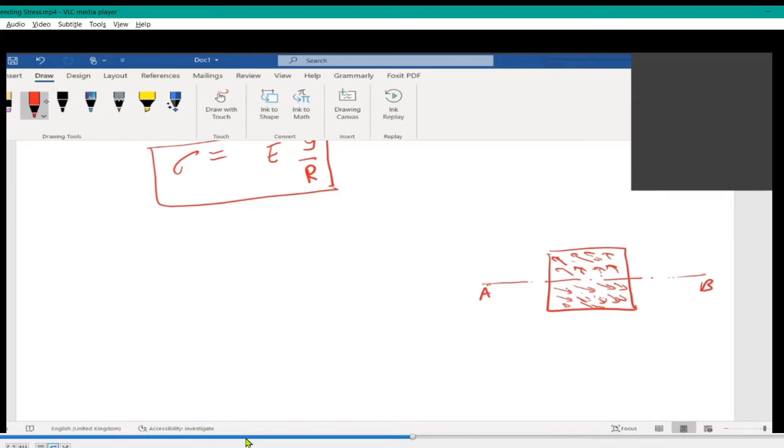Put together, we can say this is acted upon by a moment called M. Okay, net result or overall result. Right, you know that the member is subjected to compression here and tension here. That's what I'm plotting here. On top, above the neutral axis, the member was subjected to inward stress. Below the neutral axis, the member was subjected to outward stress. Overall, we can say it is subjected to a moment M.